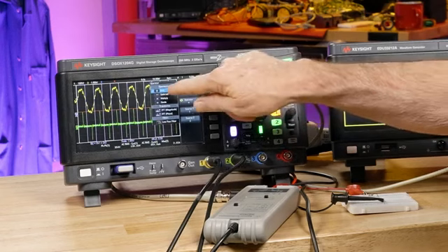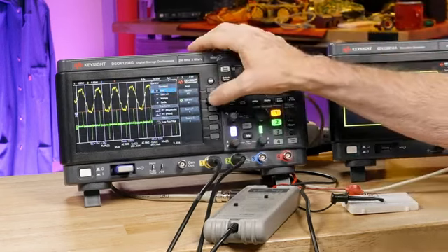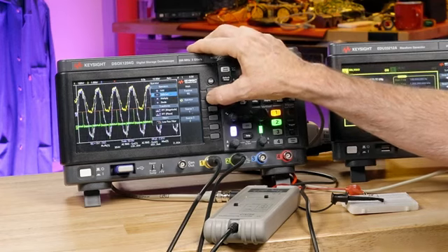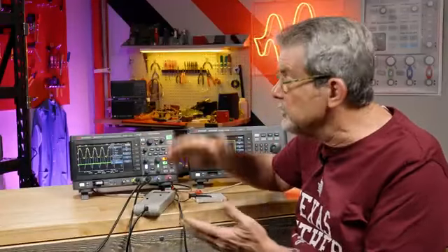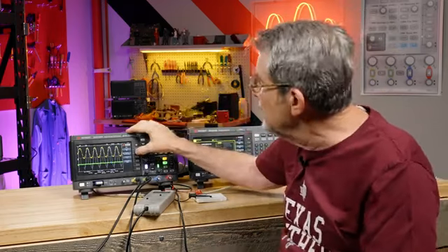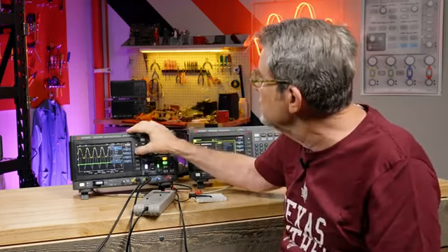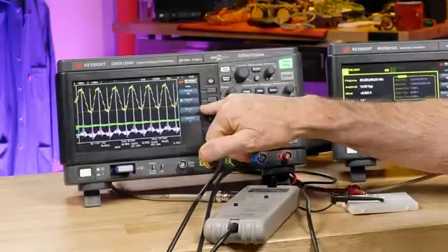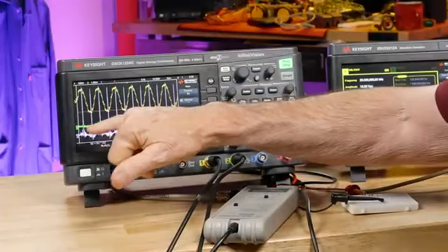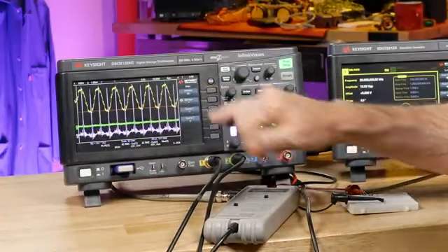So the default is add. The other selections are subtract, multiply, divide, there's a magnitude FFT, phase FFT, and a low-pass filter. Now, higher performance scopes have many more math functions, but this is probably enough for what you're doing in the university. So we need to select the multiply math function. Now it's multiplying channel 1 times channel 2 and producing this purple waveform.